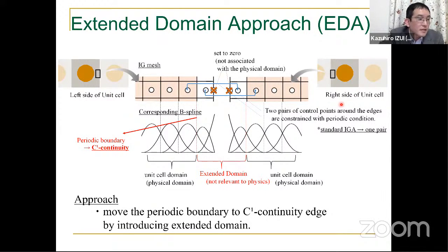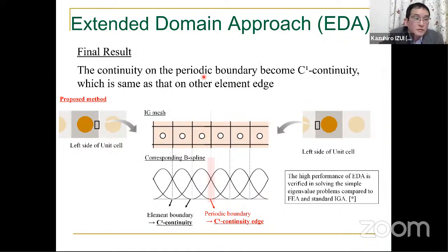And this extended domain is a fictitious domain and not relevant to physics. However, by introducing this fictitious domain, we can deal with a periodic boundary as a C1 continuity edge. So the accuracy of analysis is enhanced by using this methodology.